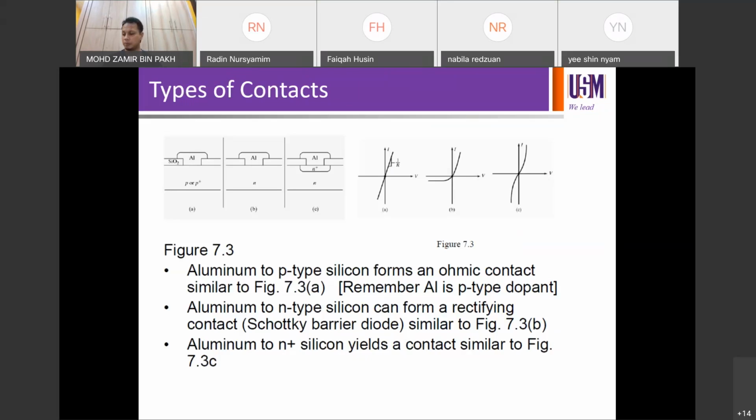One of the main purposes is to improve the contact resistance. So you want to reduce the resistance. Improving resistance here means reducing contact resistance between aluminium and your silicon. If you just have a blanket doping, for example, N layer, you're not going to get easy formation of ohmic contact compared to N plus sitting on N, for example. So it's a lot easier for you to get your